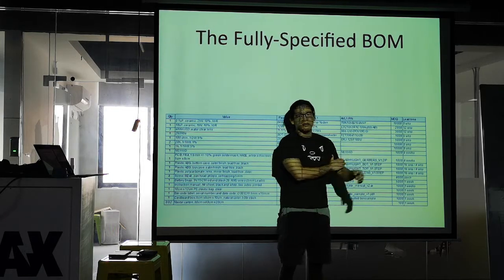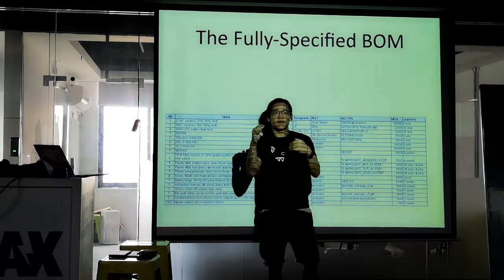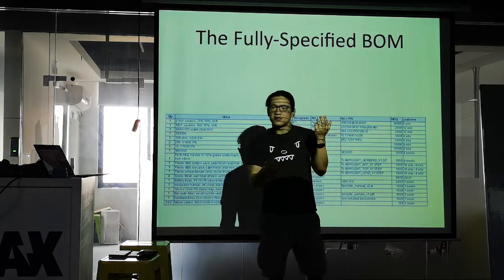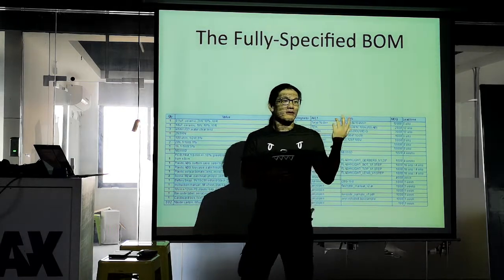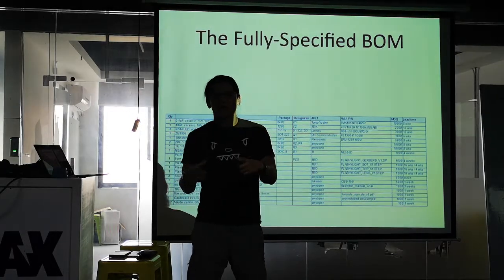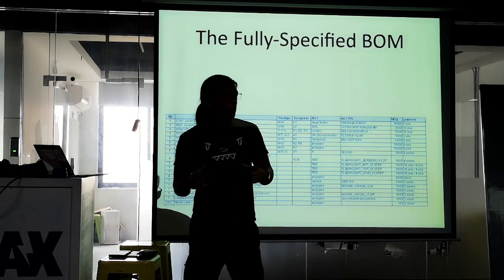Keeping track of that MOQ as you decide to scale up will help you make decisions about the volume breaks. People ask, how does someone know that at 100 units it's cheaper, or 500 units, or 3,000 units? A lot of times the reason it gets cheaper is because now someone can consume the whole reel on that build, versus trying to split a reel.